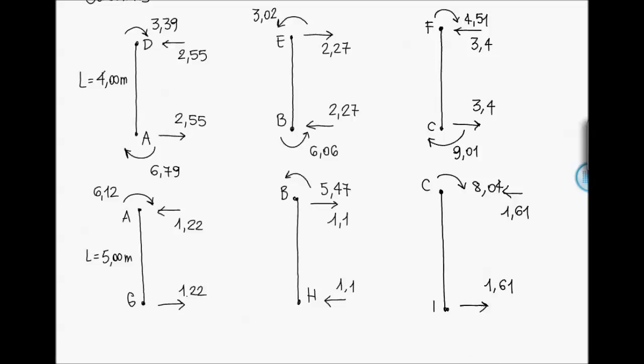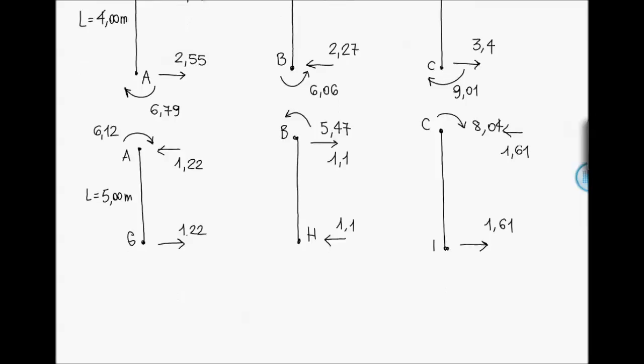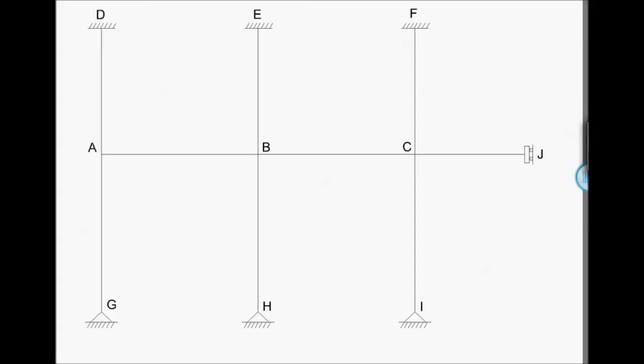Well, these shear forces, as you have noticed, are basically determined by equilibrium. Well, the sign convention for the shear is this one. If this is an elementary portion of the beam, these are shear forces taken to be positive. So we are now able to draw the shear diagram, which is this one.